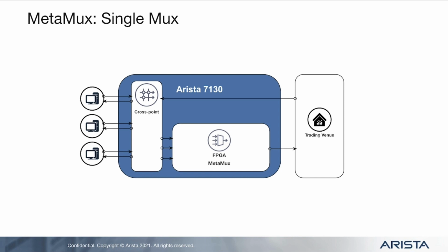The typical use for this application is for trading firms to share a trading venue handoff between multiple latency sensitive machines. In many cases, those machines themselves would use FPGAs to reduce the application latency, so the latency of a traditional switch would have a relatively large impact on the total system performance.